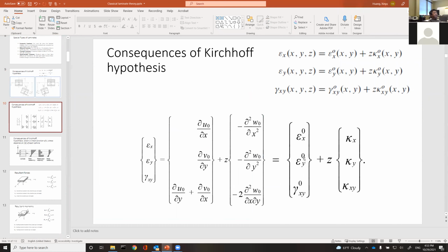It basically says, if you know the location of a certain lamina in the Z direction, and you know the mid-plane stretching and curvature, you can calculate the strain anywhere. That's strain anywhere equal to mid-plane strain plus a modifier: the height of each layer multiplied by the curvatures.